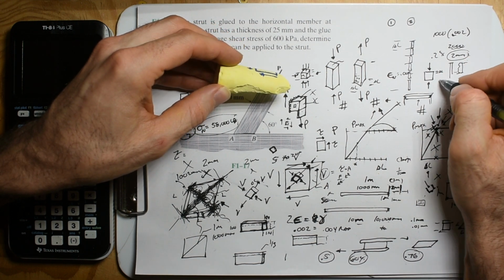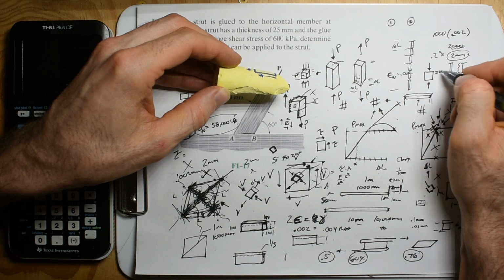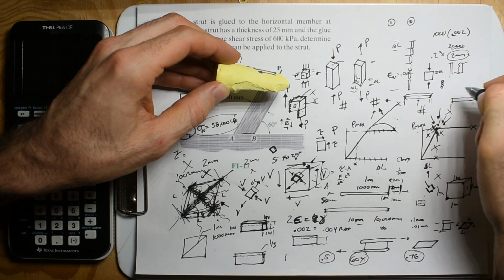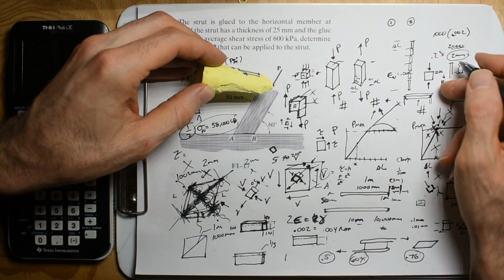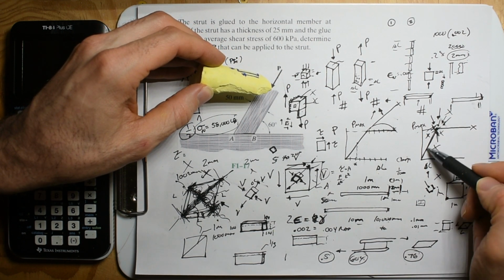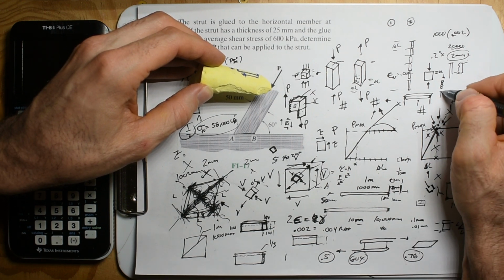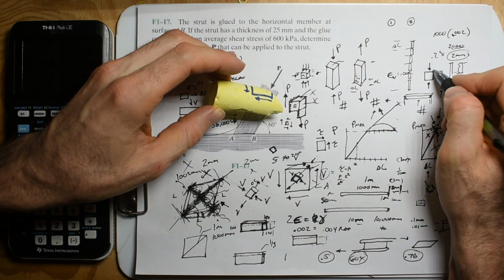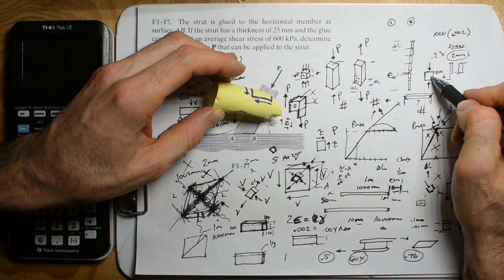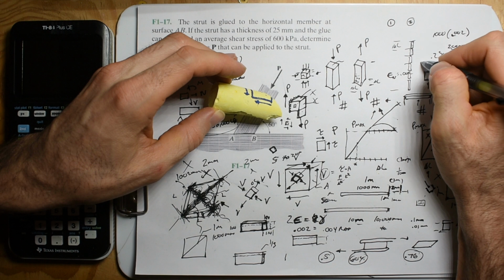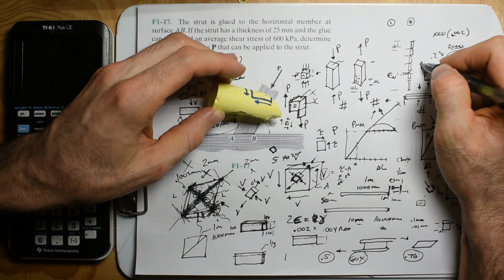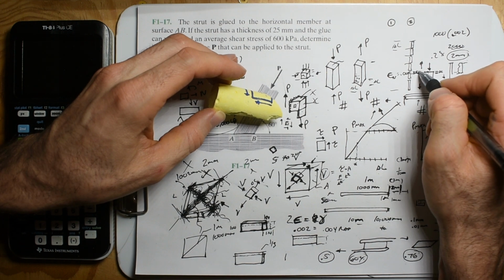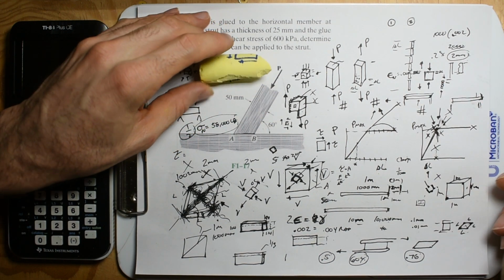Every material from a molecular level is linearly elastic when you put loads on, and in this region right here, it's all linearly elastic. So you will get a change in length of a concrete pad in compression. But take that same concrete pad and put it into tension, and you can't change its length very much.